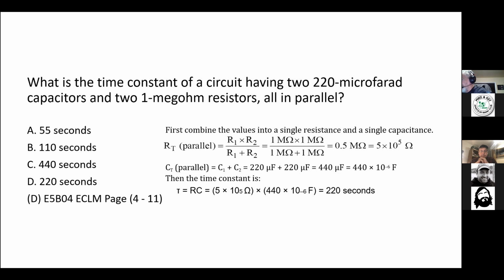Okay. Well, that's not a problem. This is Daniel, KO7WM. My sister said this: college taught her where to look, and that's what this course is going to show you. You may not remember the actual formula, but you'll know someone who does and know where to find it. The big thing here is when you turn off an amplifier with a power supply, don't put your hand in there right away, because of the time constant, those capacitors are being bled off slowly.